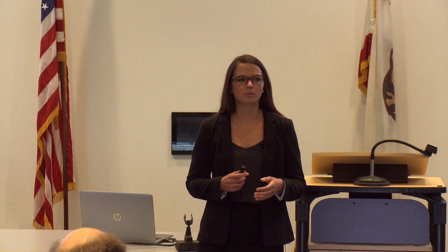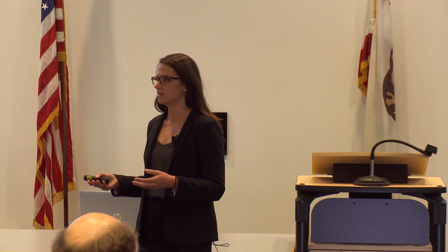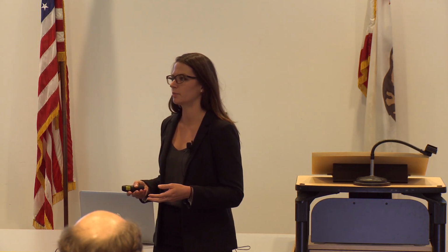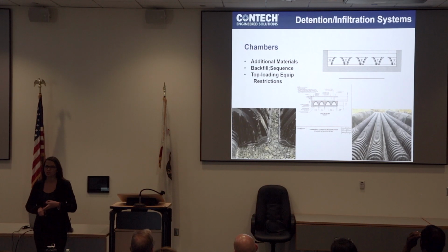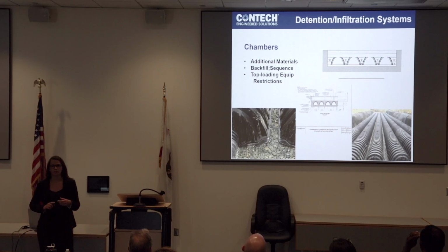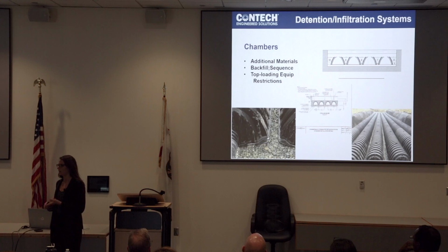Okay. Starting off with chambers. With chamber systems, there's some additional materials you need to consider. For example, right underneath the inlets of these systems, you're going to need a scour netting to prevent erosion of that leakage. Next, you are going to need your Tensar GeoGrid, your C40 non-woven geotextile, and finally, you're going to need 4-inch PVC inspection ports with caps for all of these systems.